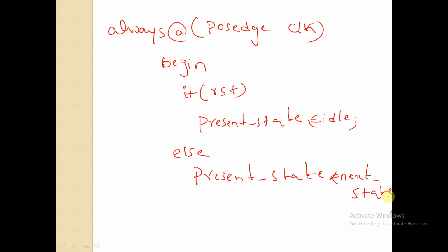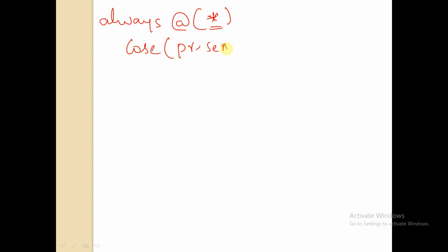Next state. Next, we are seeing about next state logic. So it is a combinational logic. So I will use always @(*), and I will use a case (present_state). So if it is idle state, then begin,